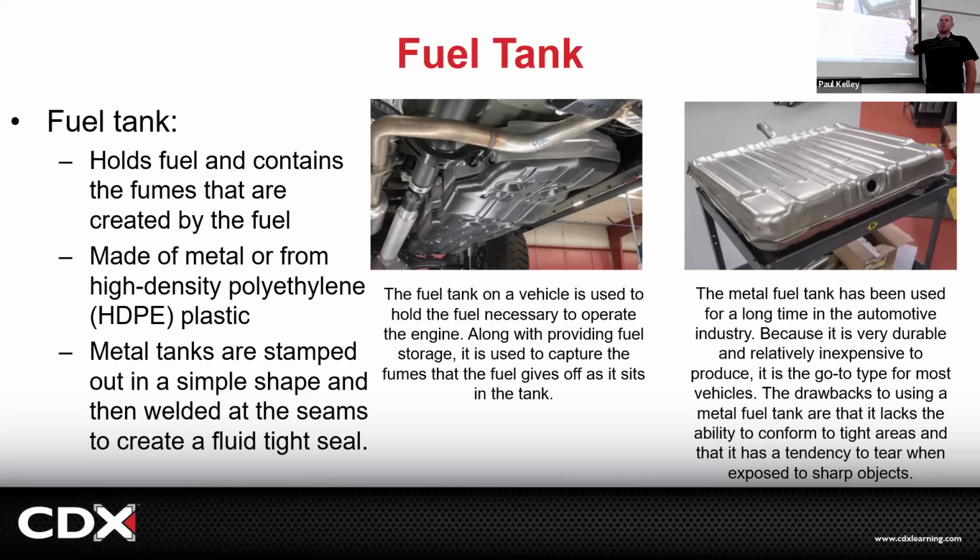And if you get rust on the outside, there's probably going to be rust on the inside. And if we get rust on the inside, where do you think that rust is going to end up? All up in the whole system, right? We've got a filter, hopefully that's going to catch some of it, but your filter can only catch so much rust. If the whole thing is rusting, that's not good. And yeah, it's going to get in our injectors and clog them.